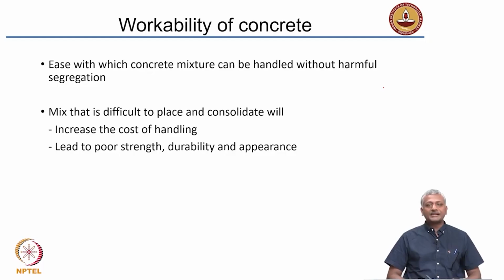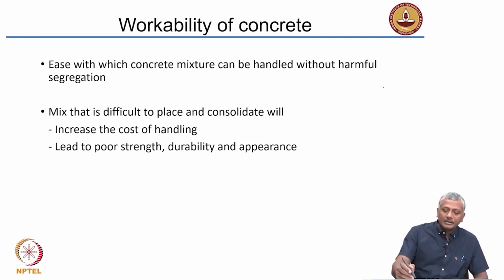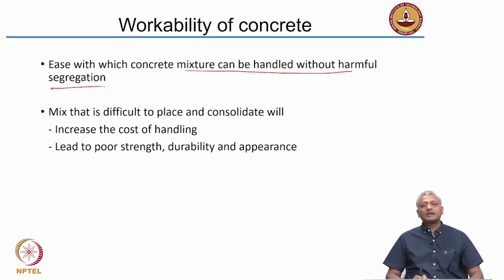So, workability, as I said, is the ease with which you can handle the concrete and place it, compact it, and so on. Generally, you say workability is the ease with which concrete can be handled without harmful segregation. What is segregation? It is a separation of the constituents of concrete.